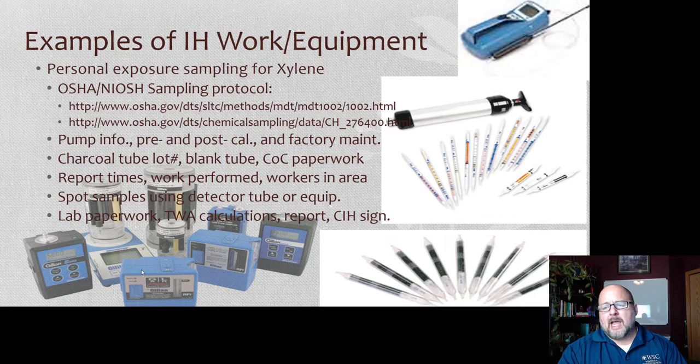This is air sampling equipment. We've got some dosimeter tubes, I guess is what we call them, and the piston pump. These are colorimetric, so you draw air through it a certain amount, and whatever chemical you're sampling for changes the color in the column and lets you know approximately how much is there. It's just an initial test, just to find out if there's anything there.